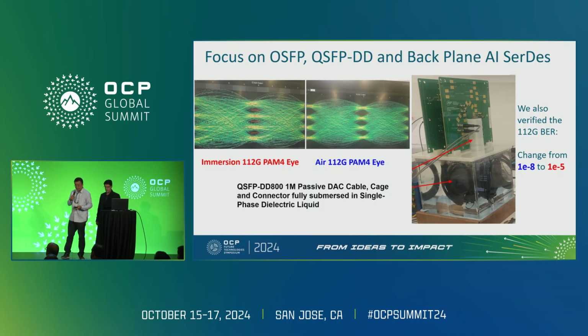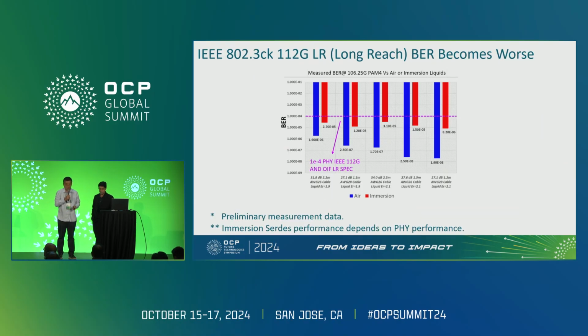So this is the eye diagram. This is what signal integrity people care about because it's really fast. So the tiny difference will have an impact on the signal integrity and the workload performance. This is testing 112 gig PAM4 per lane performance of Ethernet. The GPU to GPU also uses 112. And the latest one uses 224 per lane.